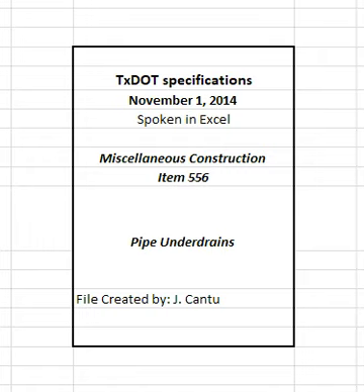Place approved plugs in the upper ends of all pipe. Cover exposed outfall ends with 1/2 inch galvanized hardware cloth as directed. Provide Class B concrete riprap, when required, in accordance with Item 432, Riprap, and details shown on the plans. Place the riprap to the contour and grade of the embankment slope. Cut the pipe to the slope of the riprap. Backfill the remainder of the trench with suitable material in layers not to exceed 6 inches.